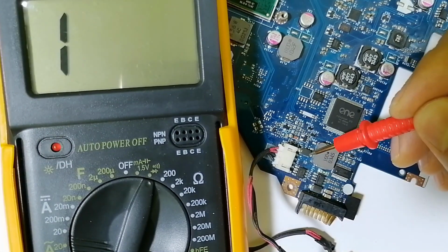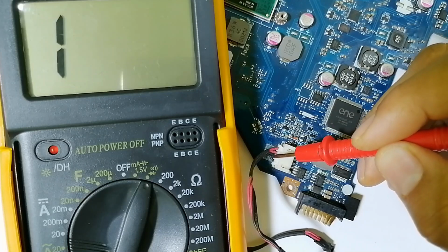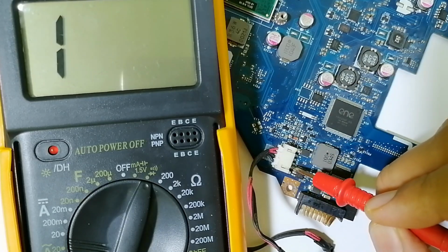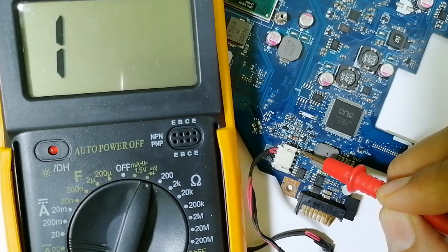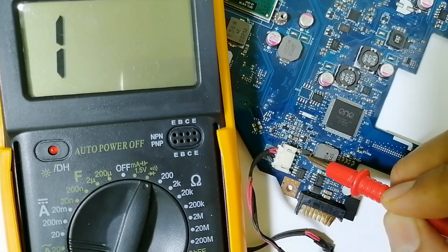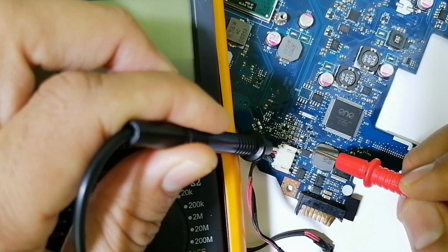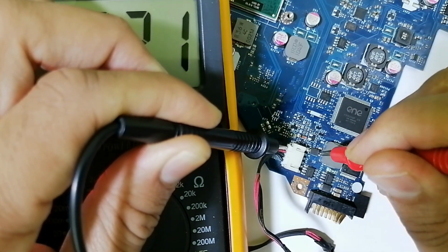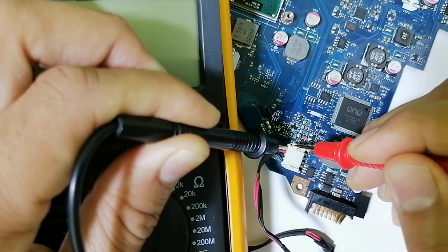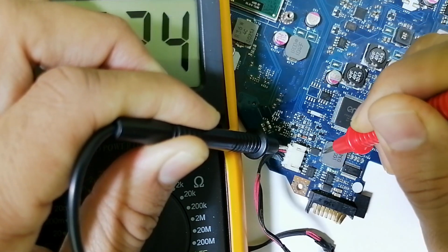Do you see this inductor? Basically here we have the high pins and over here we have low. Here we have, as you can see, these two are ground and these two are positive terminals. The 19 volt passes exactly through this inductor. So we can even check. If I put, for example, one probe here and one probe here, and check here, do you see?